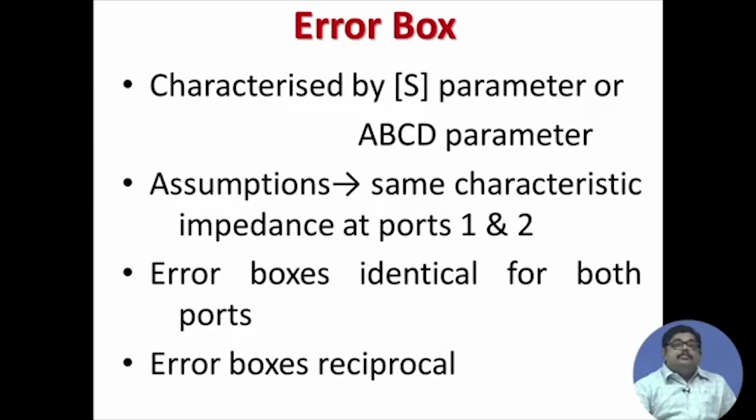That is done by putting all these errors, phase delay, etc., into a box that is called error box. So, the error box represents all these lossy or error effects. Now, that error box is characterized by S parameter. So, if we are aware that there is an error, we can characterize that error, and we will see how it is done. And in that, finding that error box S parameter,